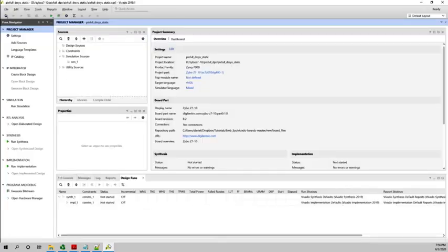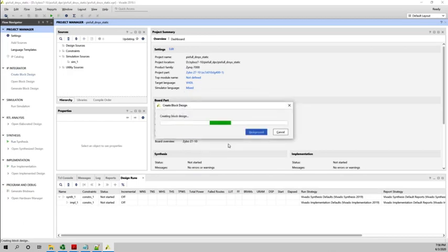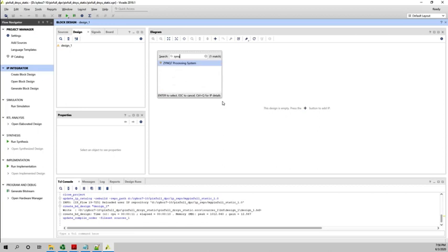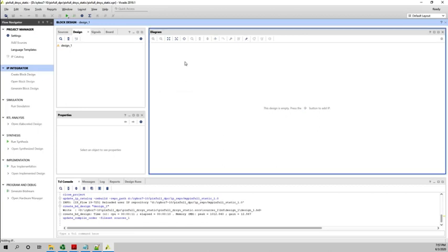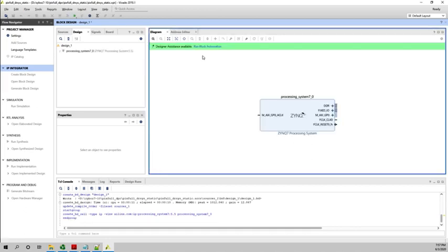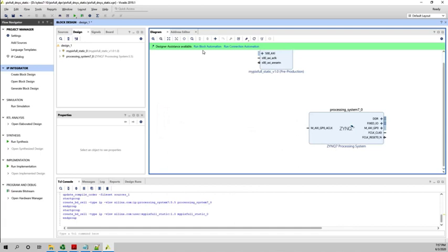And there you go. Now you go back to the original one, create a new block, and now you're going to create your block with this AXI peripheral without the reconfigurable partition. And then you're going to synthesize, and once you finish that portion, that's when you can finally get the static region description of this system you want to build. Okay, so let me just, static, nothing is changing, I'm getting ahead of myself, there you go.